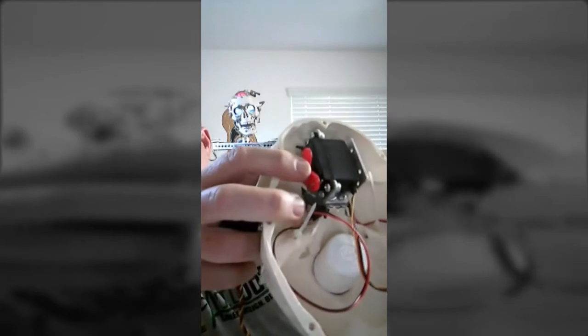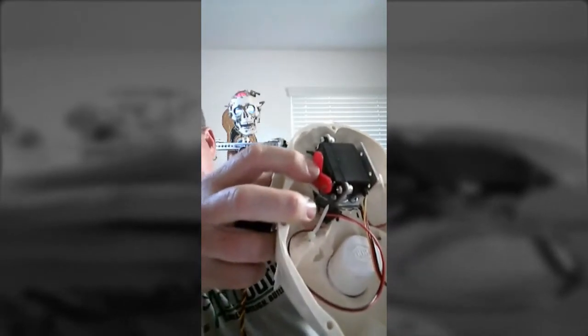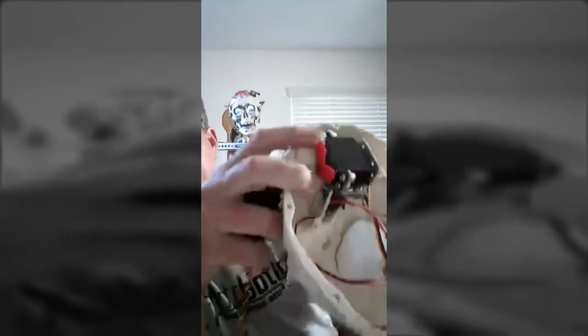Now, I like using the red horn. When you buy the high-tech servos, they come with a bunch of different horns that you can use. I like this one. This one actually comes 4 pieces as a plus sign. I cut the other 2 off and just use these 2 on there. Okay, and it's nice for me if I leave the second one on when I can manipulate it by hand. Okay, so you're going to get that servo installed. You're going to put your servo horn in.